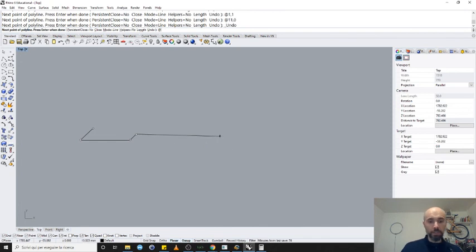But this seems to be a good opportunity to introduce you to the smart track. Now, this is a pretty cool feature in Rhino. It must not be used all the time, because it could become annoying. But smart track is basically a way to highlight a point just because you stay there a bit longer, or because you press Control, it turns the point off and on. When it's on, it creates lines that Rhino thinks could be relevant. Usually you have the vertical line and the horizontal line.